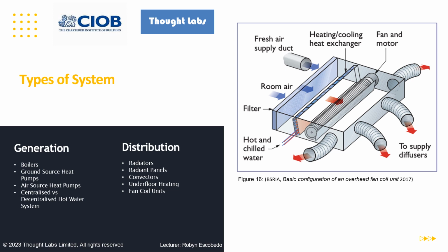An advantage of fan coil units is that they are fast to respond and so will quickly heat and cool the space. Again, we go back to our classroom or meeting room. Fan coil units may be the solution. They can be situated above suspended ceilings with grills simply at ceiling level, so again, aesthetics are not too affected by these fan coil units.